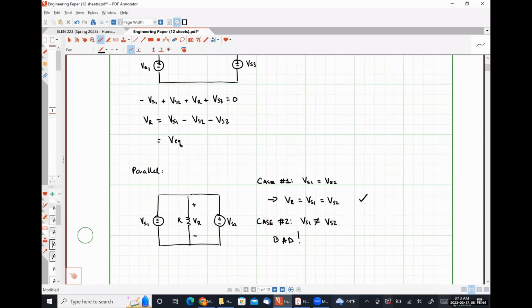All that I do there is connect batteries or voltage sources in parallel, because that's what a battery energy storage enclosure is: a whole bunch of batteries connected in parallel. And then they have a charge balancing circuit to make sure that effectively all of the battery cells have pretty much the same charge so that you're not causing particular cells to heat up and explode because they're full of dangerous chemicals, okay? So batteries or voltage sources in parallel is something that is done an awful lot in the electrical utility industry, especially alternative energy. Okay.